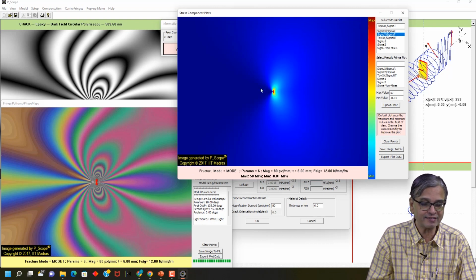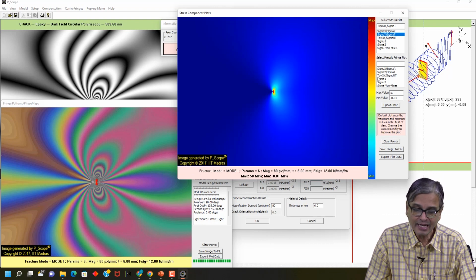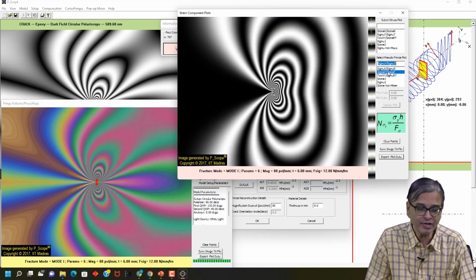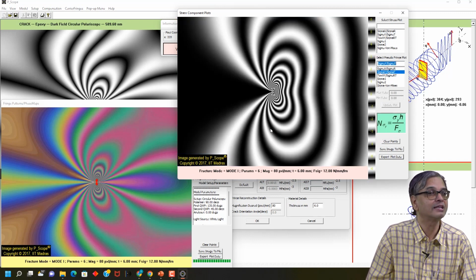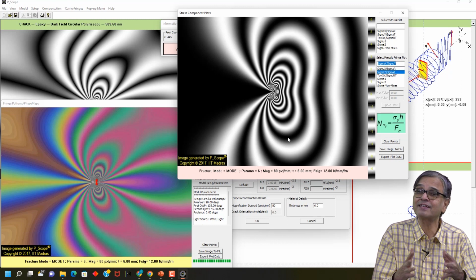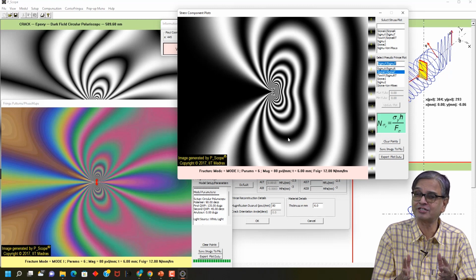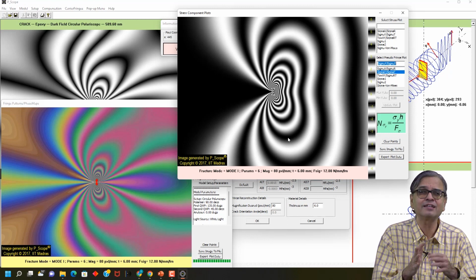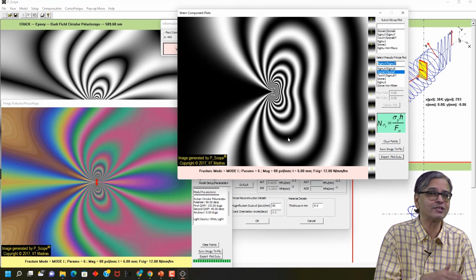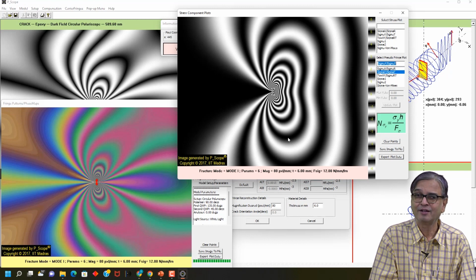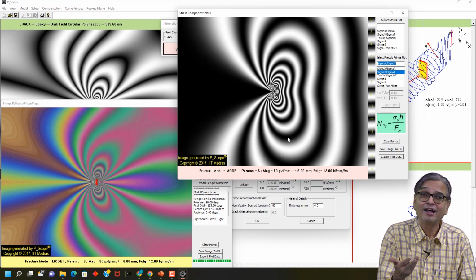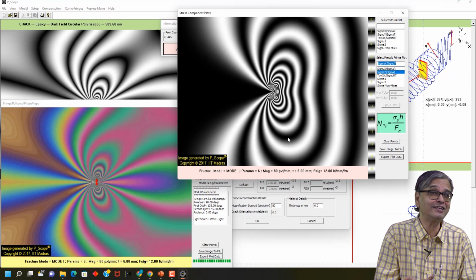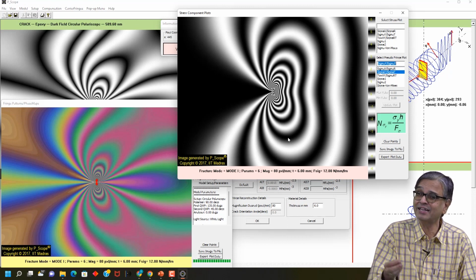And you have the sigma y stress component like this, and you also have simulated fringe contours. You have the sigma x, how the sigma x contour changes. It's all very complicated. You have a very high level of stress. The idea is, we have looked at what happens to a free outward corner. What happens to a re-entrant corner? Re-entrant corner, I said it is infinity, singular. That is what you have got. And then I can replot, so you can learn all of this.